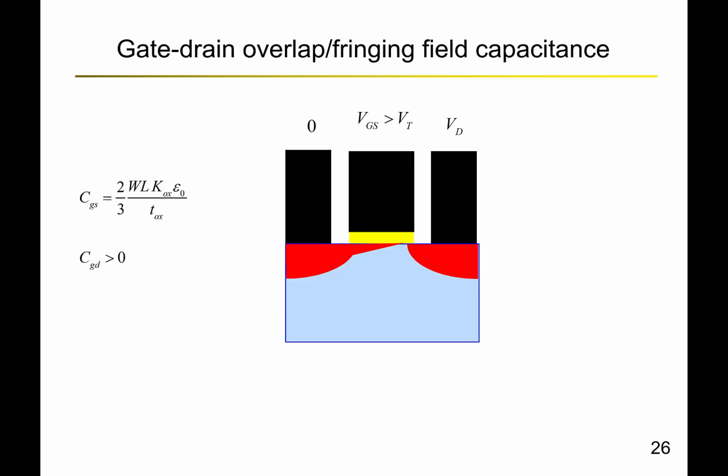That's an idealistic model, but in reality, the drain and source as well as gate have contacts which are shown by these black pillars. So the total capacitance is not only the capacitance coming from the gate to the channels, but there is also a capacitance between the gate and drain directly and gate and source directly. Let me draw this one.